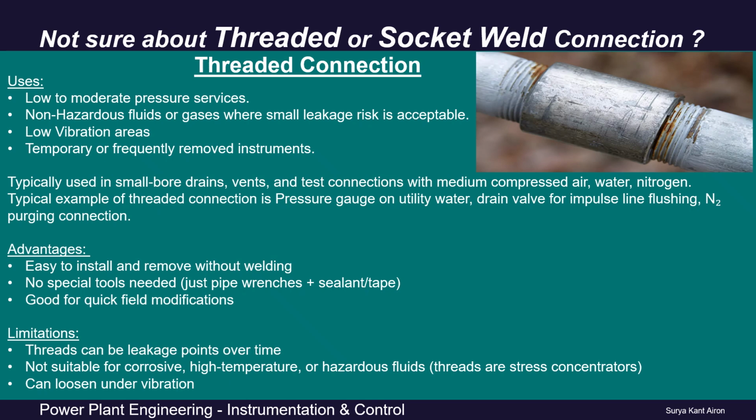And limitations, as we already discussed: first, threads can be a leak point over time. Second, it is not suitable for corrosive, high temperature or hazardous fluids. Threads are stress concentrators, and if we install it in a vibration prone area, then it can loosen under vibration.